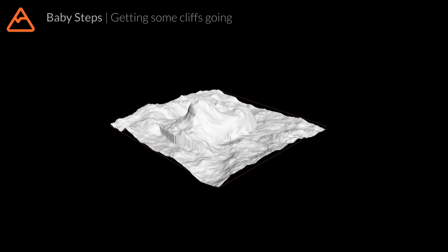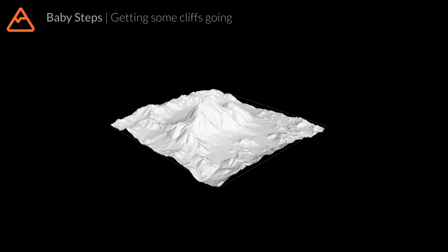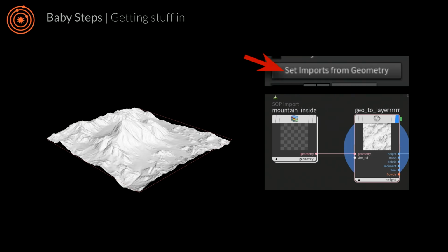Maybe add some noises, some quick erosion, some noises once again, some quick erosion once again, and now we have this little terrain. And now we can put it into Copernicus and see what kind of stuff we can make with it. In order to import your heightfield to Copernicus, you have to use SOP Import and Geo to Layer. And Geo to Layer is a node that got updated in 21. Specifically, now you can import all the layers with just one button.